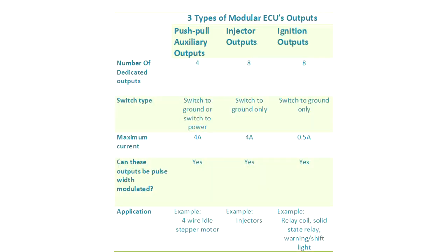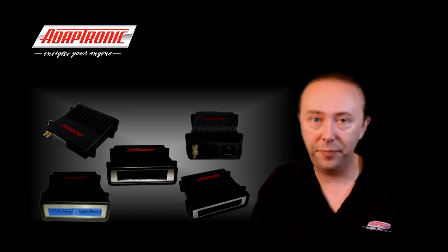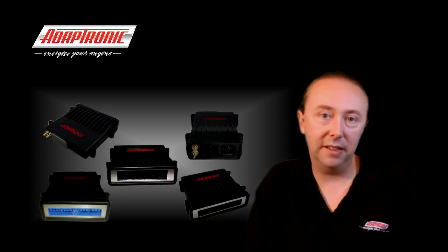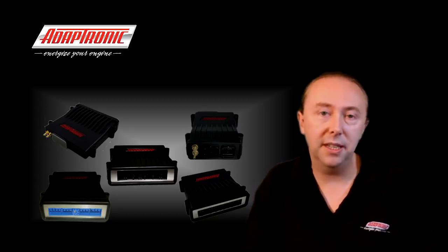The third type is an ignition output, which can also be used as an auxiliary output. In this case, the outputs can only sink half an amp, so they can be used for switching on relays and that sort of thing. This output can also be pulse width modulated, but normally the sort of things that you want to pulse width modulate need more current to drive them. The only example I can think of is if you wanted to pulse width modulate the input to a solid state relay to control a fuel pump or a water pump or something like that.